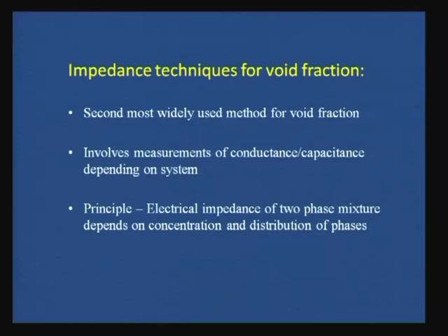And if we are operating at lower frequency, then it is based on the difference in electrical conductivity of the two phases. Usually for an air water system we prefer conductivity probes, but for certain other systems it is better that we depend on the dielectric constant difference. Remember one thing, it is easier to design the circuits for conductivity probes. The only problem is that it's very difficult to maintain a constant conductivity of the liquid, isn't it?